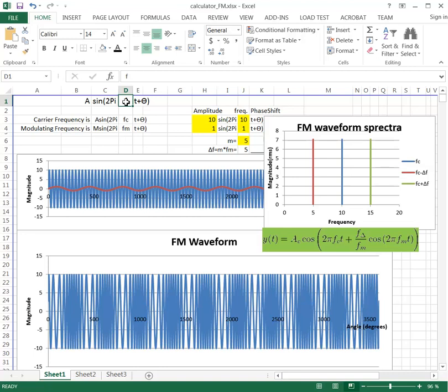If we were to have a noise spike come in here, for example, it would make absolutely no difference because there's no encoding on the amplitude of this waveform. If this waveform gets to the other end and it is only a couple of volts high down here, as opposed to the 10 that I've got shown here, no data is lost or corrupted because there's no encoding on the amplitude of the waveform.